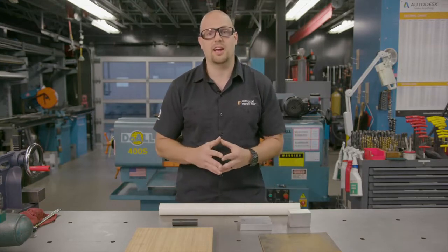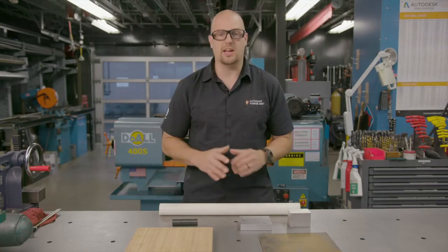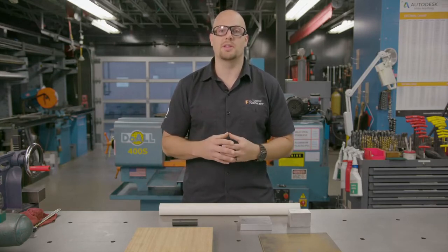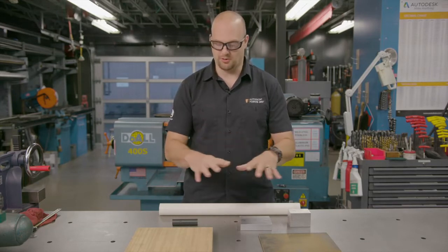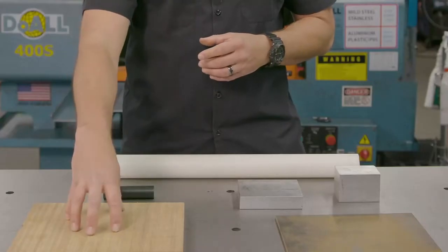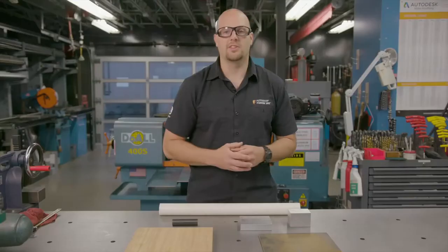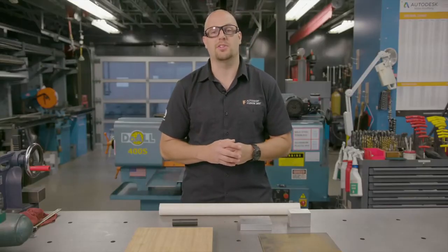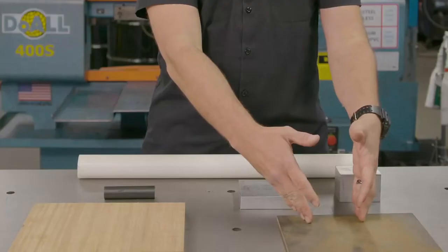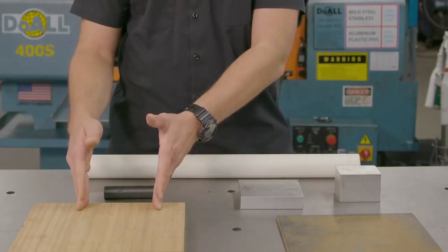Now, the other thing to understand about stock is something that we call machinability. All of these different types of materials will have a different machinability level. You can find machinability indexes on the internet to help you understand the machinability of different types of materials. For instance, wood is going to be softer than aluminum, which is going to be softer than steel. So the machinability of those 3 materials is going to be very different, which means I'm going to have to be less aggressive removing material from a piece of steel than I would be removing material from a piece of wood.